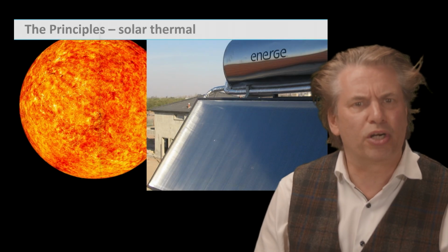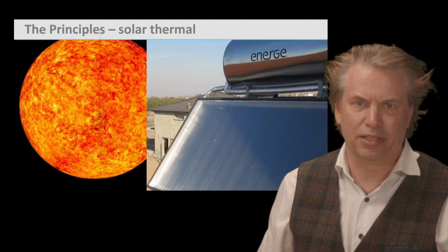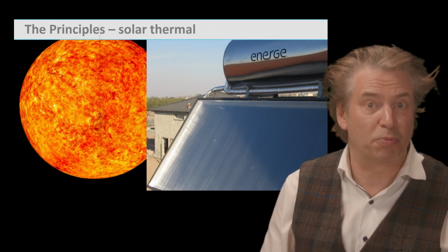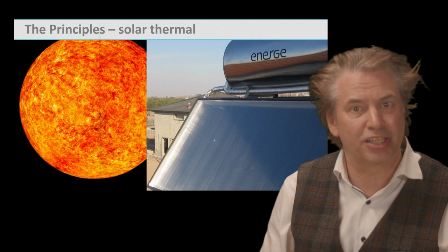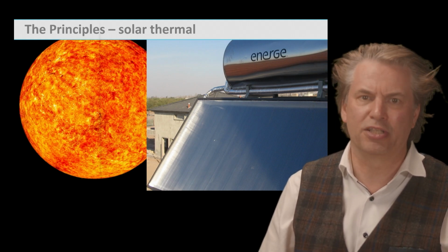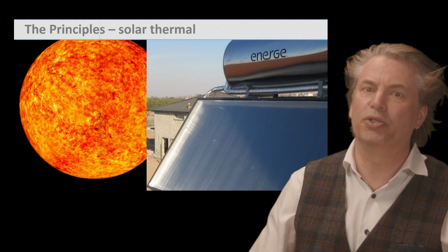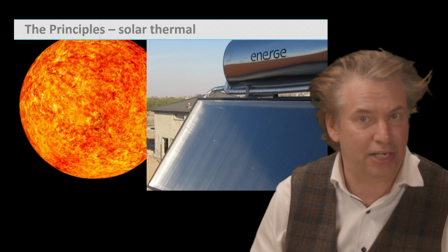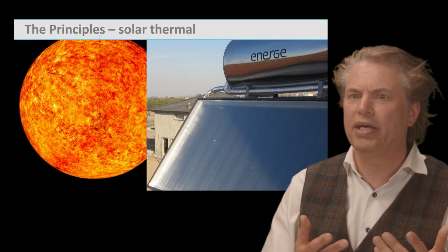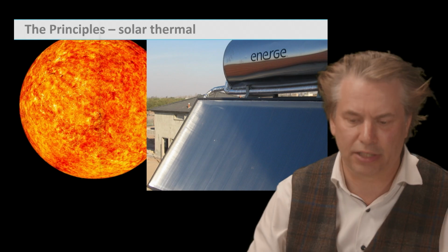In thermal solar, the solar radiance is converted into usable heat. Like this, a solar collector operates on the principle of absorbing solar radiation and converting it into thermal energy, heat, to heat a working fluid, typically water or antifreeze. The fluid circulates through the pipes and the thermal heat can be either stored or used. We will go into more detail on this technology in the exercises.